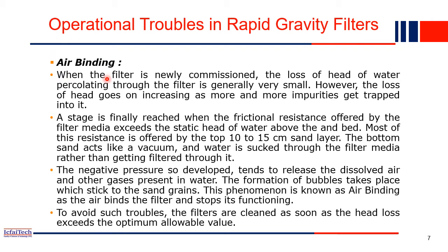The first problem you will find is air binding in the sand filter. What is air binding? When a filter is newly commissioned, the loss of head will be less, generally very small. However, the loss of head keeps increasing as more and more impurities are trapped in it. As the pores in the sand are filled up with these impurities, the head loss will be more, right?